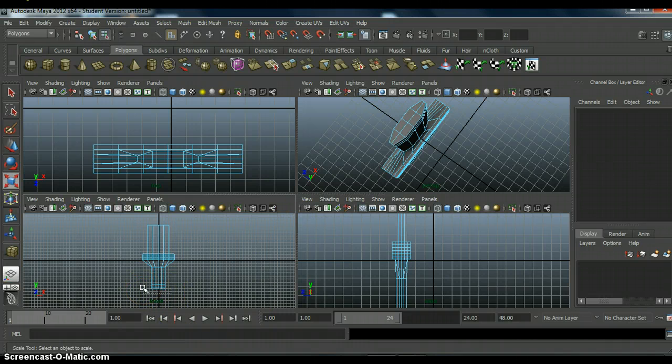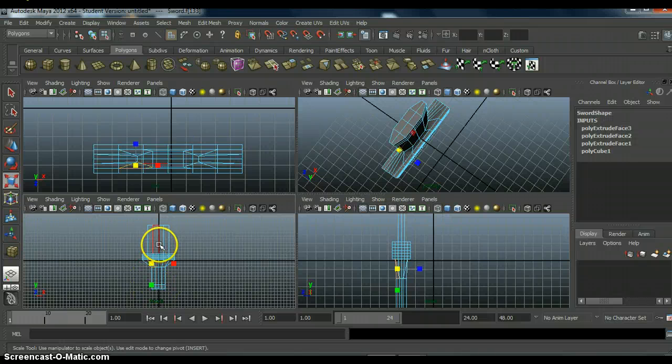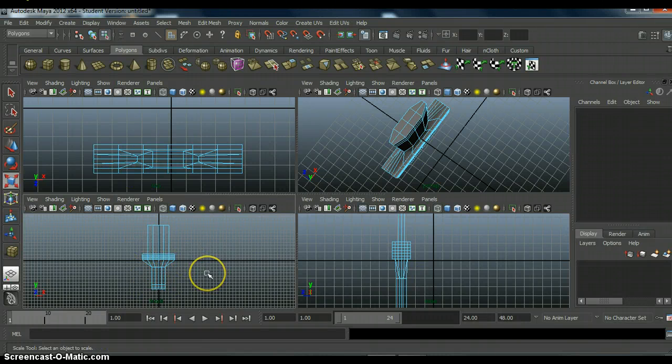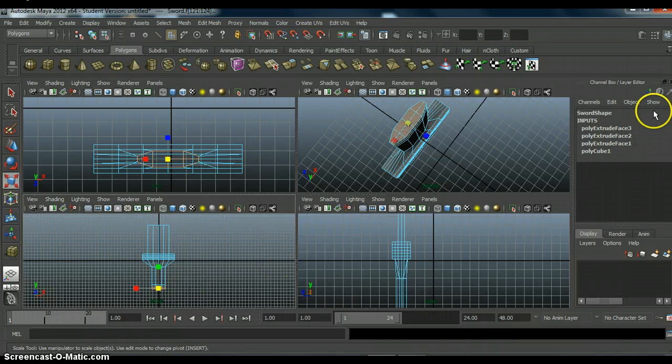You don't necessarily have to go select the select tool in order to create a box, or say select the face. It can be done easily just by clicking on anything you need. So right now I want us to create a box at the bottom of the handle, over the faces on the bottom of the handle.